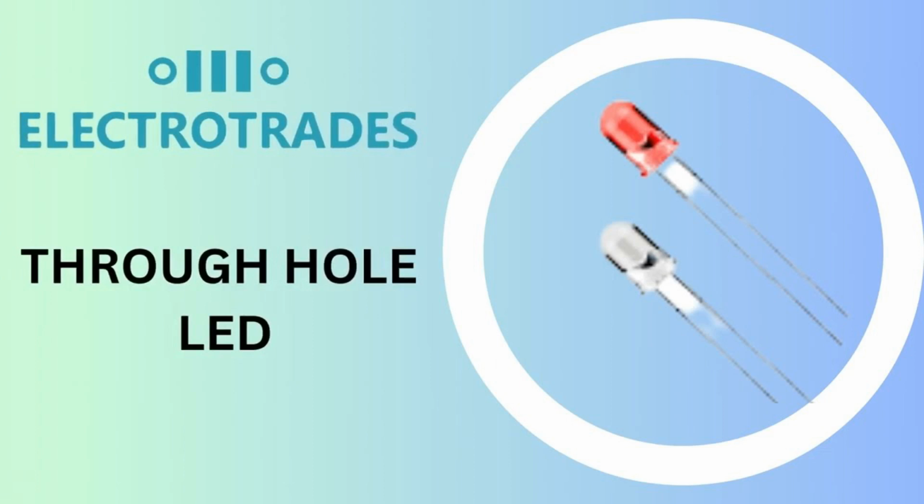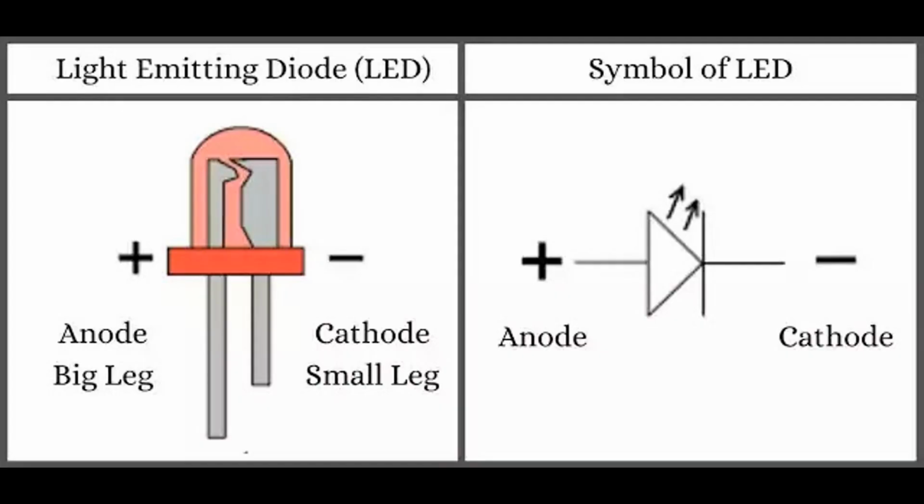The energy band gap is a crucial concept in solid-state physics and semiconductor materials. It refers to the energy difference between the highest energy level in the valence band, where electrons are bound to atoms, and the lowest energy level in the conduction band, where electrons are free to move as charge carriers of a solid material. In a simplified model of electronic band structure, a solid material's energy levels can be represented as energy bands. The most important energy bands are the valence band and the conduction band, which determine the material's electrical properties. Here's how the energy band gap influences the behavior of materials.